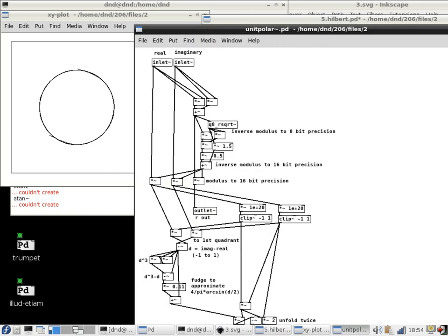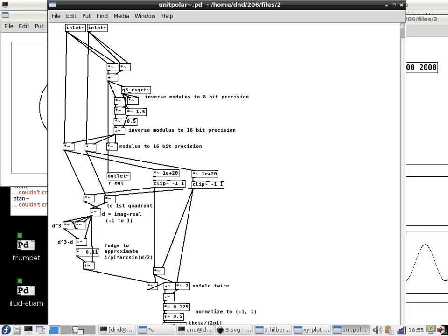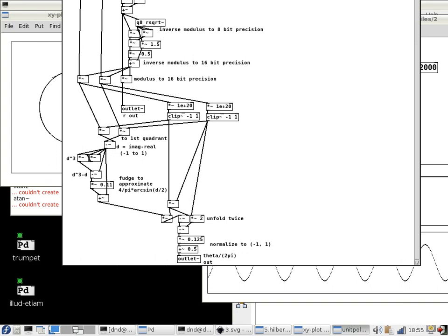Since I don't like doing trig, since I was raised on DSPs that didn't have trig functions, here's computing the modulus. Those of you who code DSPs, I will tell you how this all works if you're curious. And here's how to take the arctangent. So first off, you're going to fix the modulus. All right, so this is taking the square root and dividing it out so that you get a point which is on the unit circle from the point which is on whatever circle it was on.